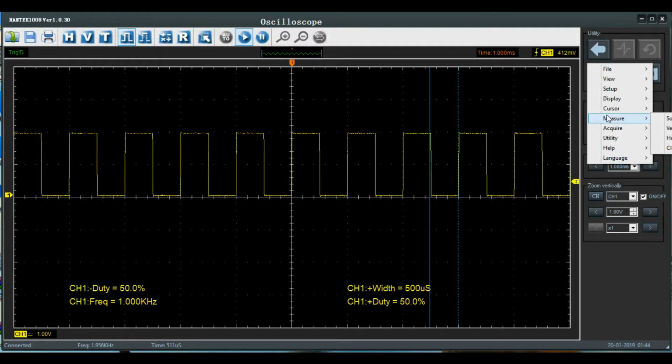Because the Snap-on actually gives you everything. It tells you everything. And also with the Snap-on, it doesn't give you as much information as the Hantek does right off the bat. You actually have to record your video, and then you can take your video and go analyze your video, and then you'll be able to get all the information that I'm getting right here on the screen. Now, it doesn't mean that the Hantek is a better oscilloscope, not at all. It's just that for me personally, if you want to actually get to learn how an oscilloscope works, this seems to be the better choice so far.